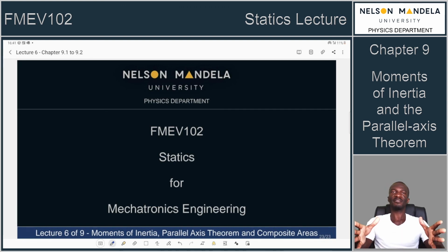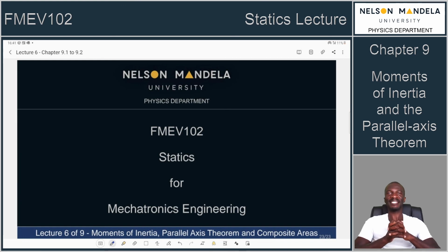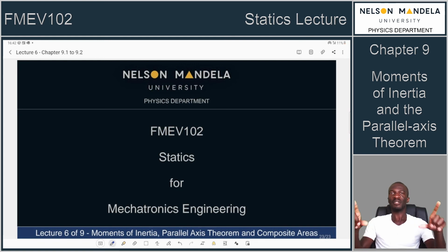Each of these moments of inertia have an associated radius of gyration. And the radius of gyration is simply that distance which we need to locate a compressed version or a compressed geometry of the original area parallel to the axis of concern, such that we get the moment of inertia that is exactly as we would find for that original area. That sums up this chapter.